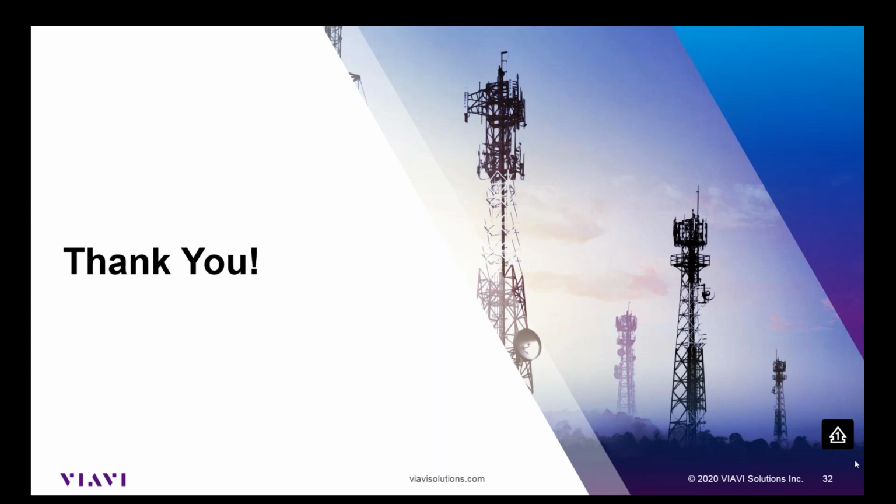It was well below that, and they tried adjusting it up, and this was manually. So it's not just an auto test thing; it happens in manual tests as well. But they had the soft pot maxed out, and we were still well short of 100 watts. And I asked them, hey, what's your cable loss? And of course, everybody kind of scratched their head, because years ago nobody really considered the fact that the cable has loss. I think everybody knows that, but we don't really think about it.